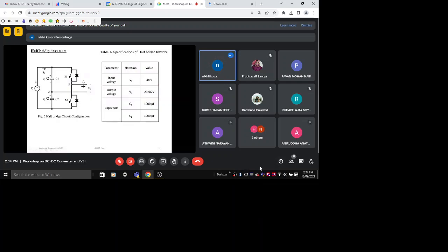So for C2, now again with the thumb rule, you can go for 100 microfarad, a thousand microfarad each. If you want more energy to be given to the load, if it is very low frequency operation, in that case you may go for 4700 microfarad also. So the value of this capacitor depends upon the load cycle. This value is enough.